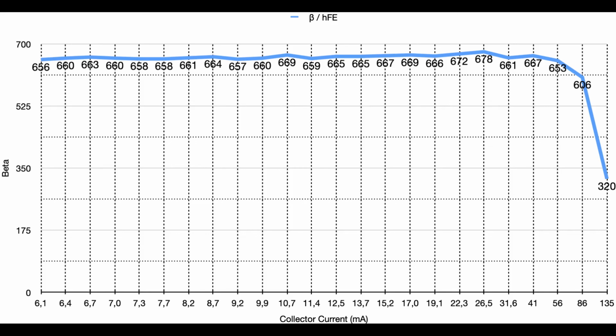And that's two different angles which you often want to see when you look at a transistor. One, okay, I put that current through the base, what do I get at the collector? And otherwise, okay, I want to drive that current through the collector, what will be resulting in the base, or what do I need at the base? So lots of questions answered from two different perspectives, and both graphs are helpful. But still, the graph's the same, only on the x-axis we replaced the corresponding collector current values to the former base values, so no new insight here from the numbers, just a different view on the topic.